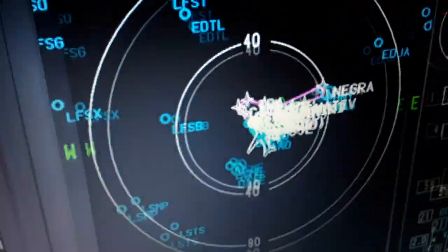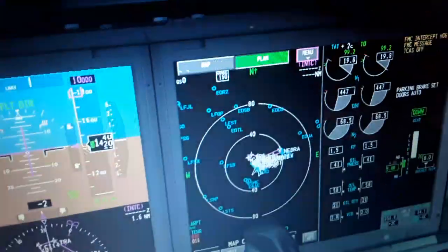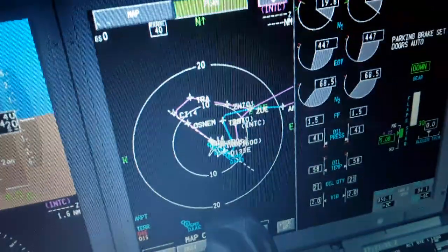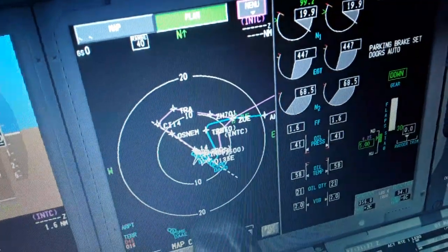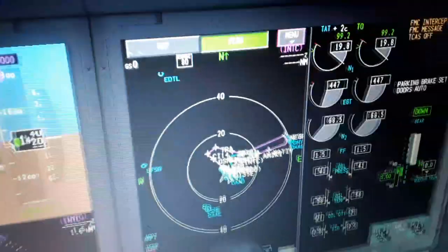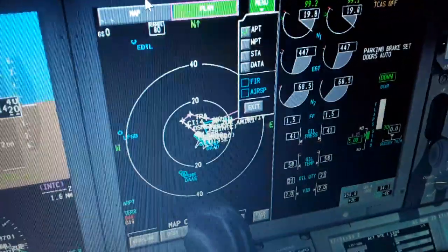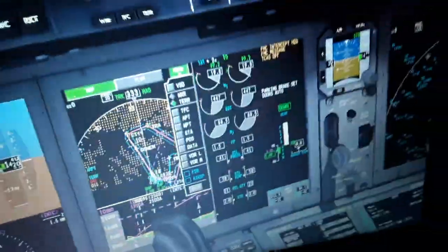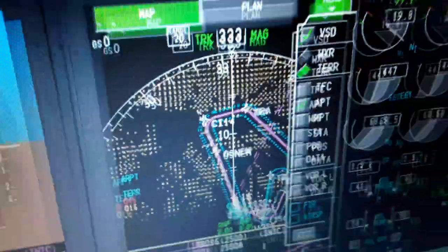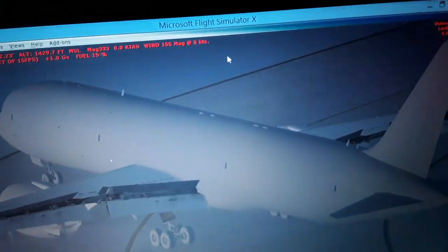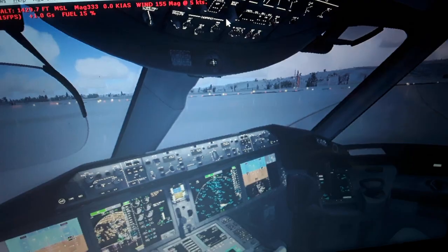See map centering. We're gonna use the ILS localizer for landing, so you can see a better view of the flight plan right now. We're gonna be flying through these waypoints we can follow from the LNAV. So we need to make a few more settings over here. Just before going to take off, we need to set up the flight management computer.